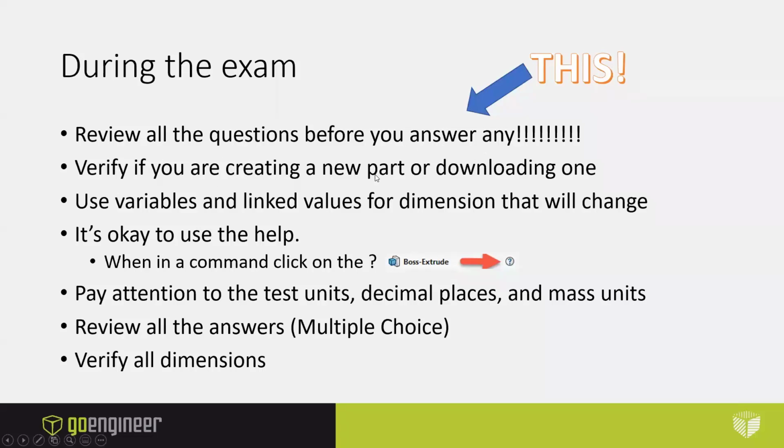Verify if you're creating a new part or downloading a part. I've gotten caught with that where it showed me a part, it had all the dimensions. I just immediately went in and said File, New and created the part, and then later on realized that I was actually supposed to download a part that had the sketches already created, and then all I actually had to do was extrude those. The test is timed. I wasted a lot of time creating the part when I didn't need to.